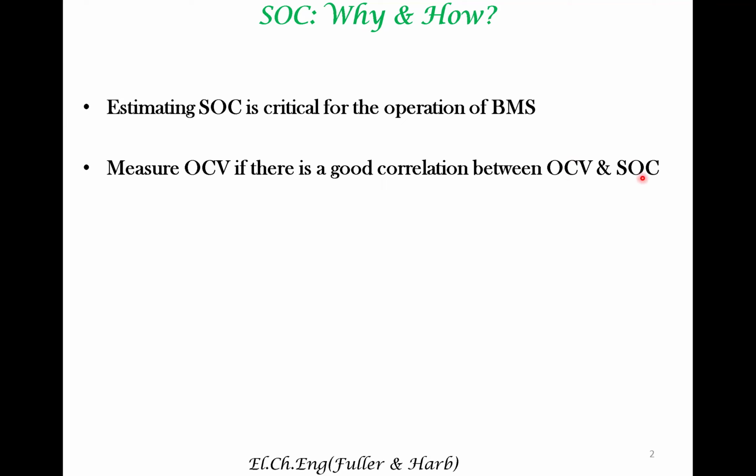Many times, it may so happen that for different SOC, you more or less have the same OCV. So just the measurement of open circuit voltage is insufficient to provide information on SOC. In which case, there are other approaches.